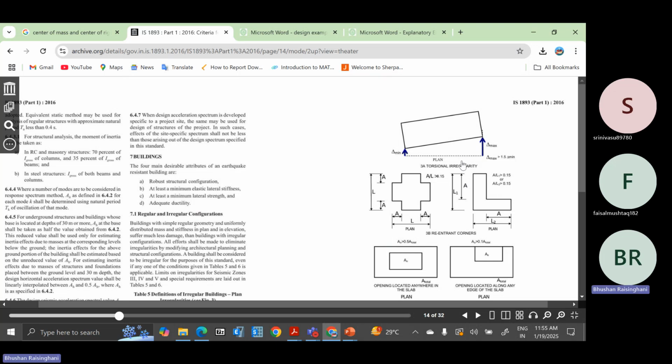This is a deflected shape of the building under lateral load. So as per the distribution, let us say there was a core wall here. More proportion of the stiffness has come here. So your CR is located at this point. And your CM is always at the symmetry, the center of mass in this particular direction.